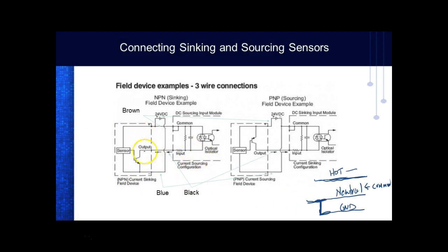This, I wanted to show y'all, this is a sinking system. And what you got to do right now is just look at these transistors that switch. That's all they do. They switch. But instead of you going up there and flipping the switch, they are what? They are electronically controlled. So if this guy here closes, if I close this switch, this is going to connect this guy to what? To minus, right? If this guy right here closes, this is going to connect to what? It's positive. That's what you got to do. You got to look at the switch.